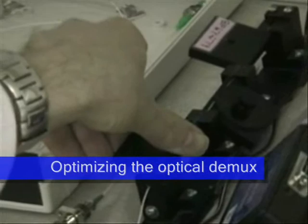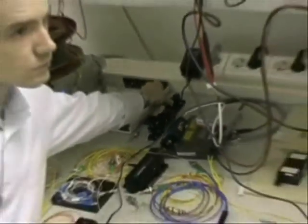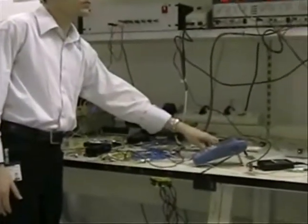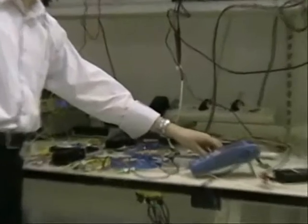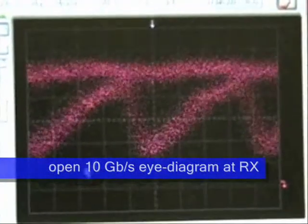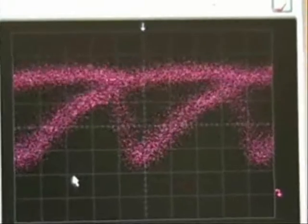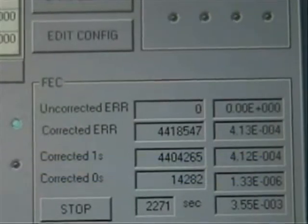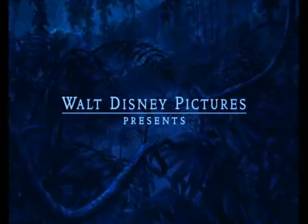On the other hand, a good setting of the demultiplexer, with an optimization of the polarization state of the received signal and with the correct position of the pump used in the OTDM demultiplexing stage, allows obtaining a well-opened eye diagram with a considerable reduction of the errors at the receiver. In this situation, the forward error correction is able to correct all the errors and to maintain a high-quality transmission.